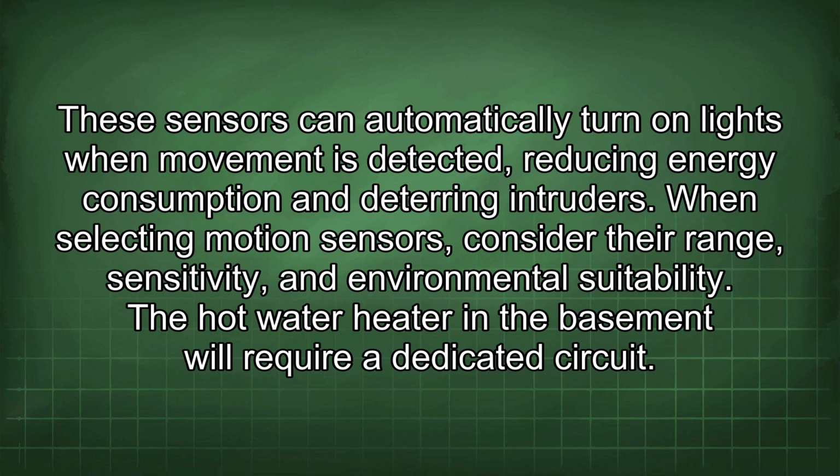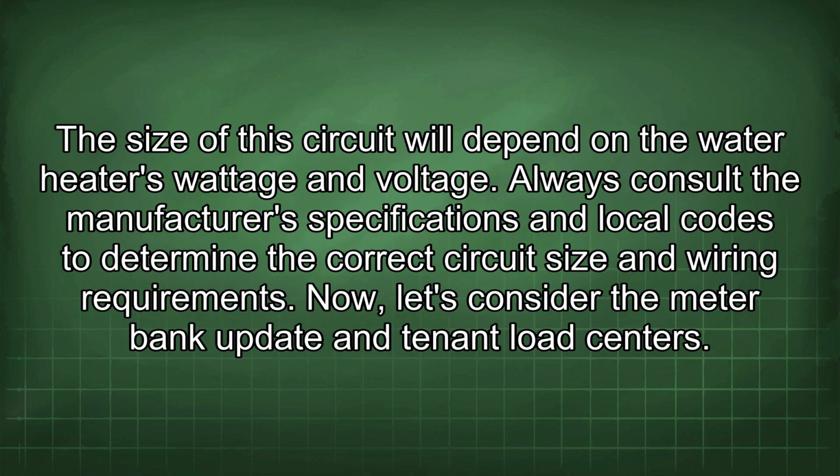The hot water heater in the basement will require a dedicated circuit. The size of this circuit will depend on the water heater's wattage and voltage. Always consult the manufacturer's specifications and local codes to determine the correct circuit size and wiring requirements.